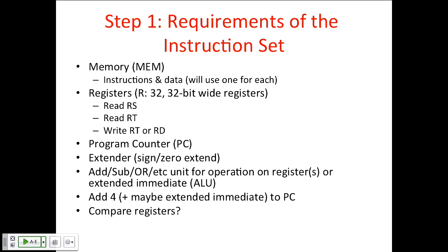Other things, what are the requirements of the instruction set? We need a memory. Actually, we really should have a unified memory, like I said, but for now we're just going to split it into instruction memory and data memory. Keep our life simple.